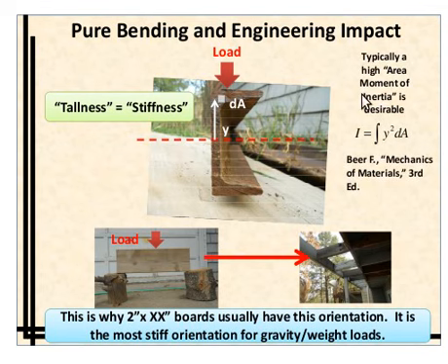So what I want to do now is talk a little bit more about that area moment of inertia term, the I that was on the bottom there, because it's kind of important. Since I is in the denominator, what you want typically is an I that is very large, so that for a given applied moment you have lower stresses in the beam. And the lower the stresses are, typically the lower the strains your structure will see, and in turn the smaller the deformations of your structure are going to be. So typically you want to have a high moment of inertia.